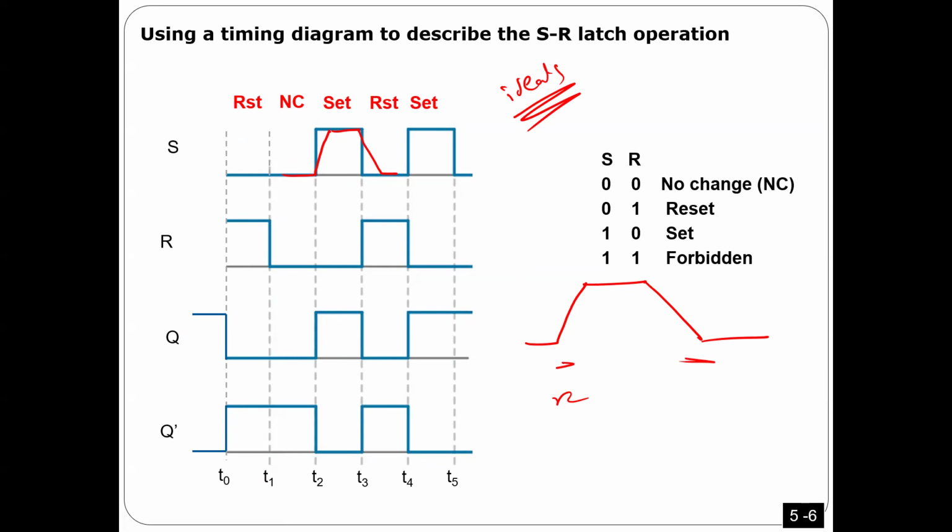Not only that, same thing here. There should be some rise time here. Also, there is a delay. Because what I'm saying here is, once this one becomes 1 and this one is 0, right away this one will be 1. What you see in the labs, that's not true. There is a delay. So in reality, it has to be this way. This one should increase a little bit. It takes some time. Also, this one should not start from here. It should maybe start from here. You understand what I'm saying? It should start from here because of the impact of the delay.